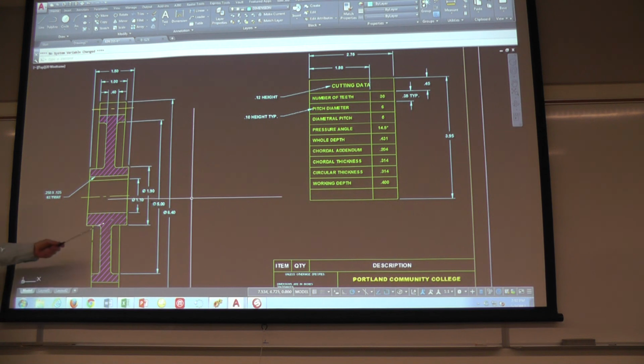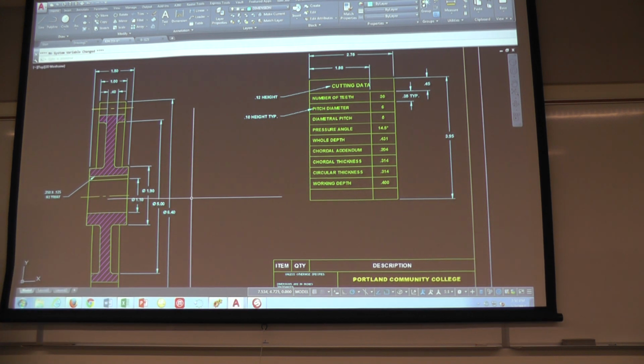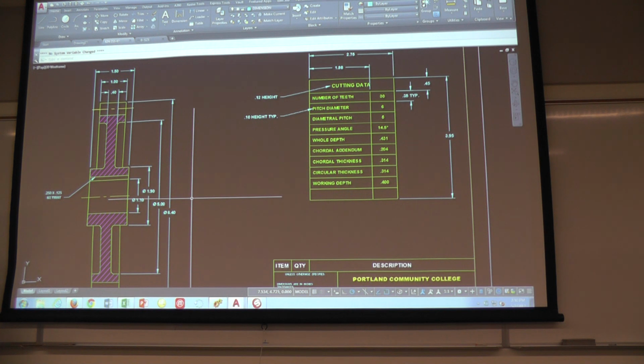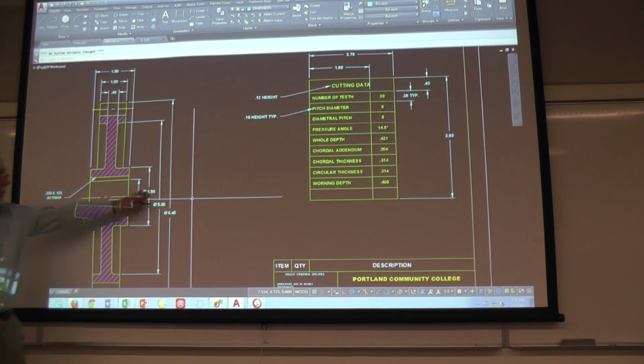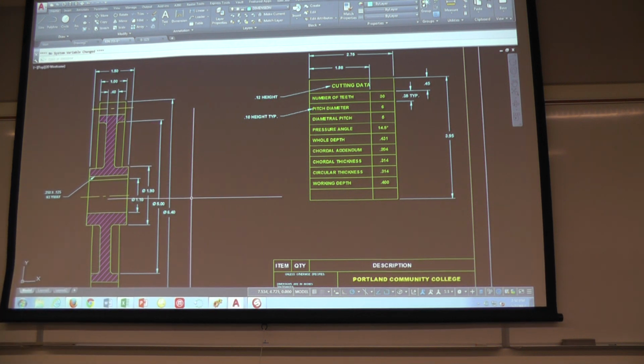Don't forget your diameters in here. You're going to have to add the diameter symbol because this is a linear dimension. You need the %%C. That drives me crazy as much as anything else that you don't, because those are diameters on there. A simple note on here, 0.25 by 0.125 keyway. 0.1 in your dimension style. You've got a dimension style requirements sheet that you should go to.